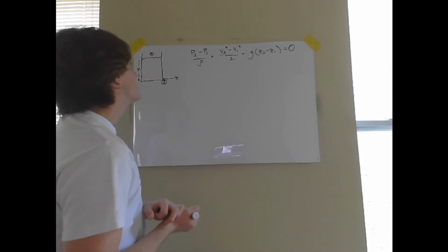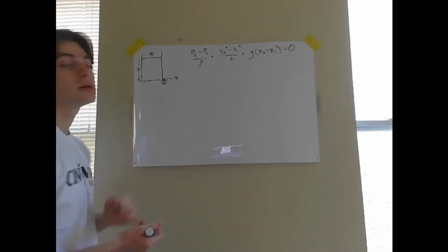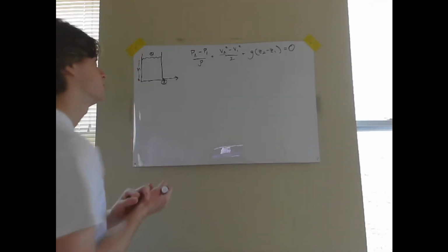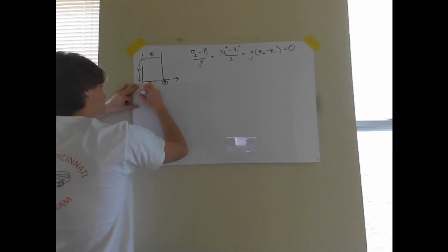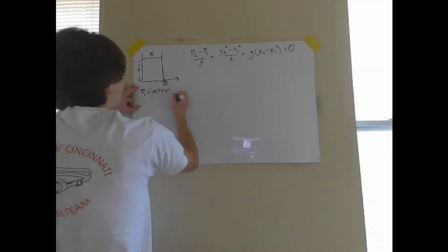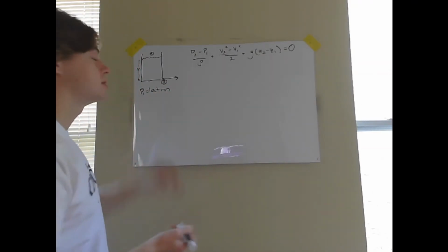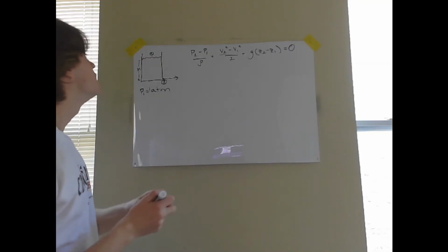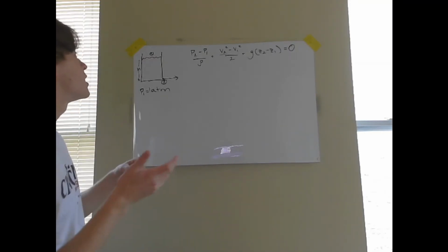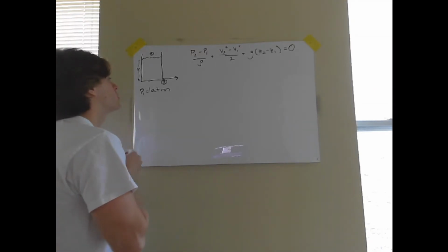So I guess our first step is we need to define the 2 different pressures. Well, P1 is easy. It's just open to the atmosphere. P1 is going to be atmospheric pressure, 1 atmosphere. Right, the top of the tank is open to the atmosphere. So the pressure at the top of the tank is just going to match the atmosphere.